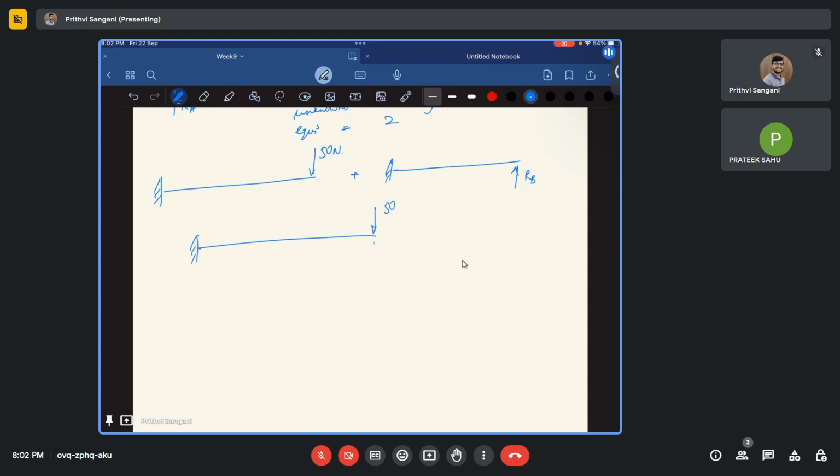Now you have a reaction happening at B because of that spring. If you take the free body diagram of the spring, let us say this is my spring, RB. It is going to compress the spring in this direction, and you have a reaction at RB here. So if you can just find out RB, then the spring gets compressed, and that is what the support reaction is.